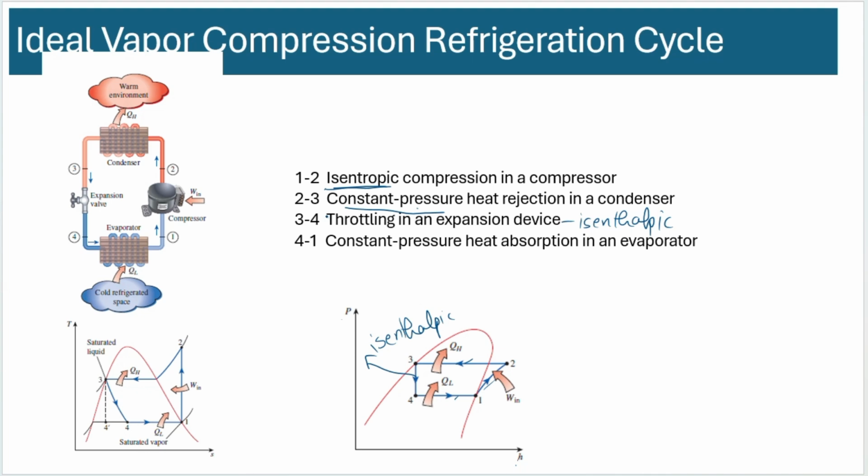So this is the Joule-Thomson type expansion, where you're keeping the enthalpy constant and then expanding. You could also see that we are inside the dome for most of the processes, except compression.